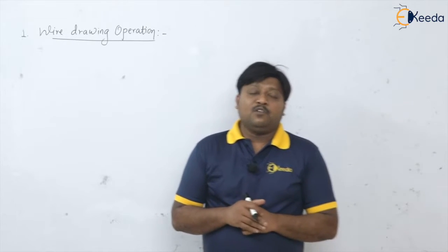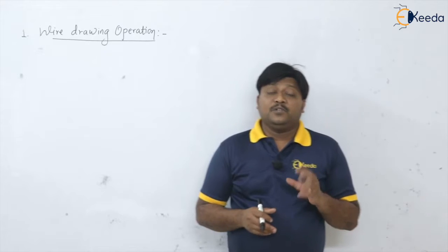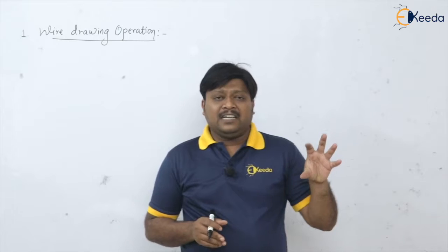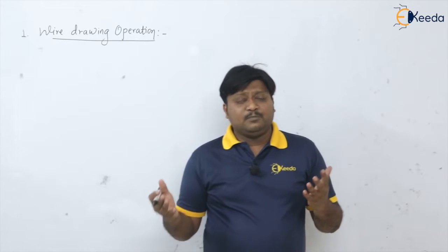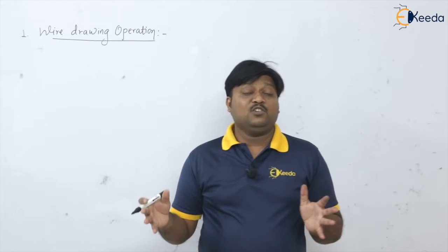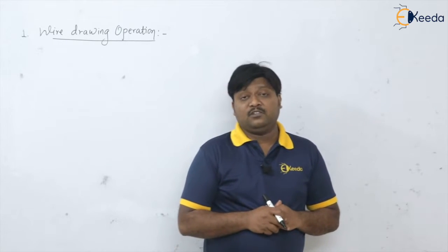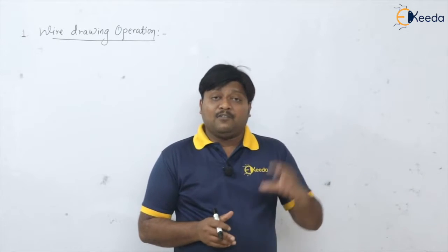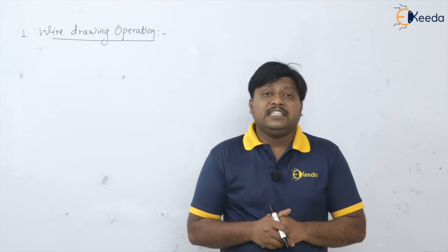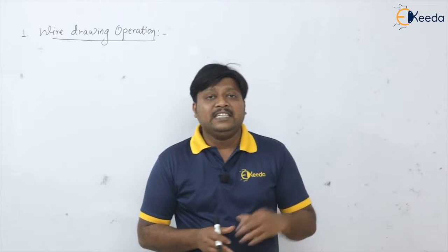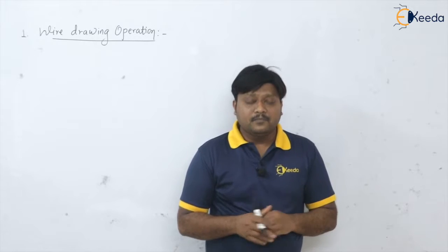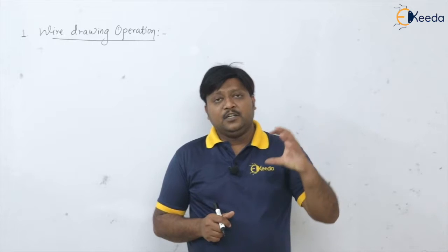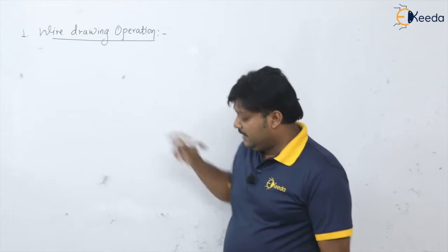So definitely, for the deformation of the given rod we are going to use the die. The die is generally made of high carbon steel or high speed steel; depending upon the size of the wire we select the material for the die. This die has the conical portion for the deformation and the straight portion for the sizing of the wire. But of course the main thing is that the deformation happens in the conical portion. So let us see the diagram.